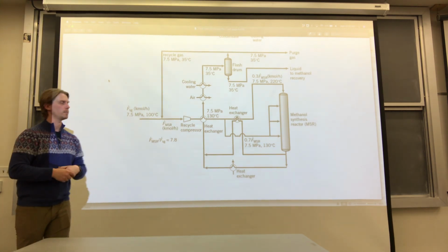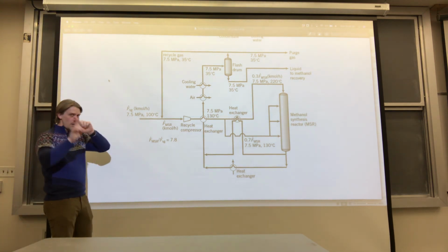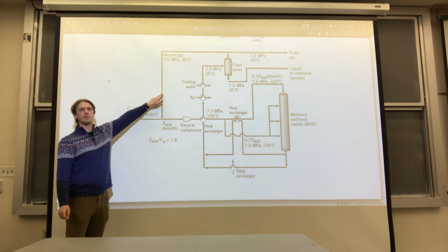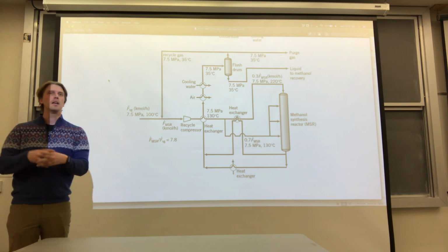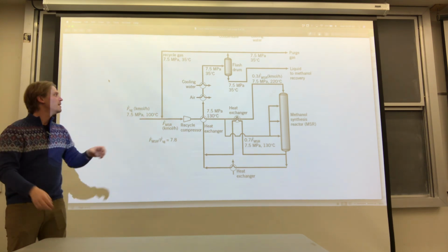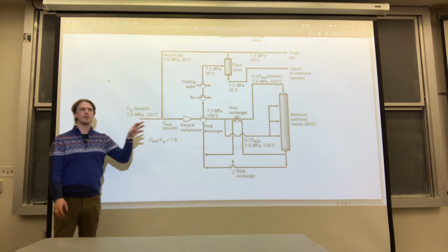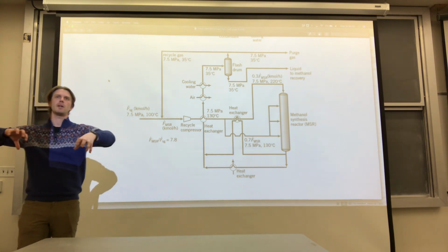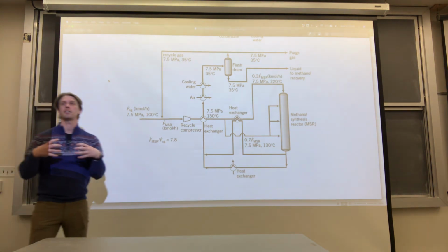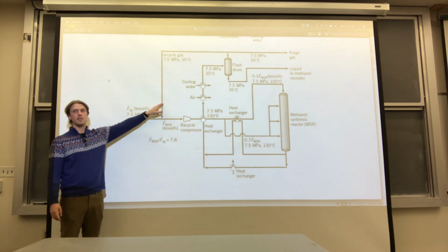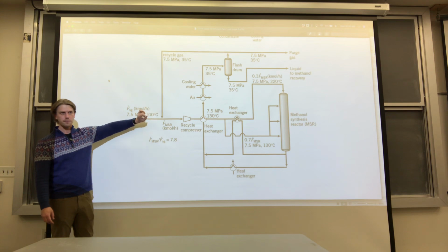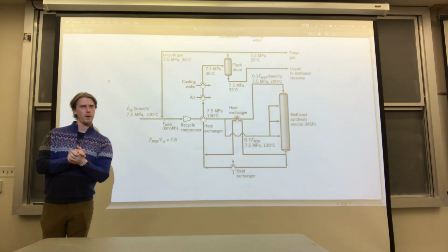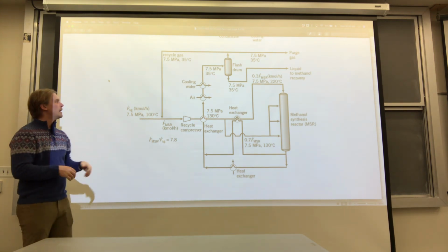So I tried to make that clear in the project description. Now, the challenge here is that you don't actually know what the composition of this stream is. The reason they have the recycle ratio fixed like this is because they control valves, right? These are gas phase streams, so we can control the relative volumetric flow rates. But we don't necessarily know what the composition of this stream is, but we're keeping the recycle ratio as the design specification. So this introduces a tricky way of how we can solve this.